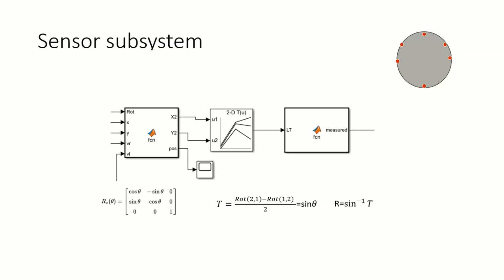In this idea, I wrote code in a MATLAB function to find the location of each sensor every second in the simulation, and to check if there's an item in front of each sensor. I wrote a formula to add specific ranges to each sensor position, and check that new position with a binary lookup table that I've created from my 3D room.